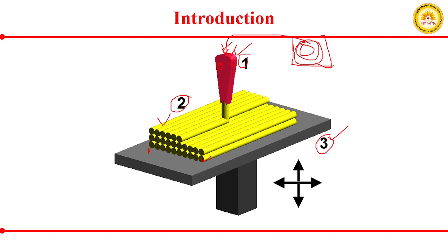Sometimes a few layers are created of your support material if you have more than one nozzle. If you have a single nozzle, then a few porous layers are created with less density, which means they are not as close to each other as in your actual build part.